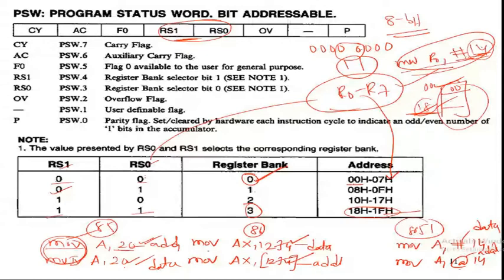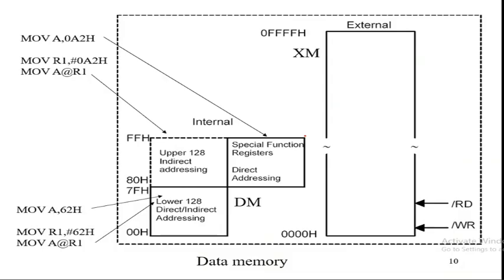Likewise we identify which one is the data and which is the address. The MOV mnemonic is not going to be changed; the representation of the number is what changes. Here we are not changing the mnemonic, we are using symbols for representation of data and address. That is a hash for data and @ for address. Okay, this is about register selection bits.